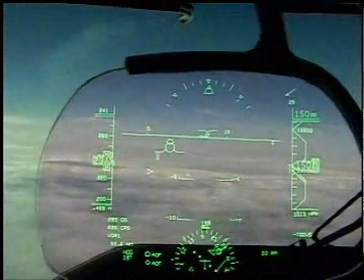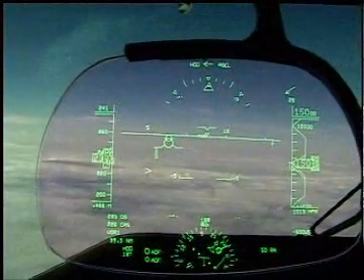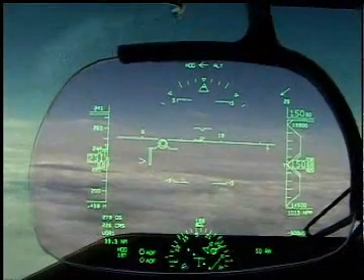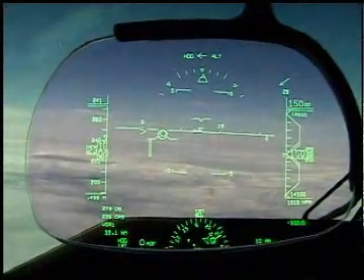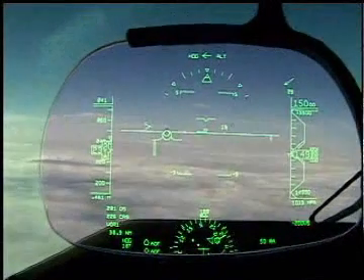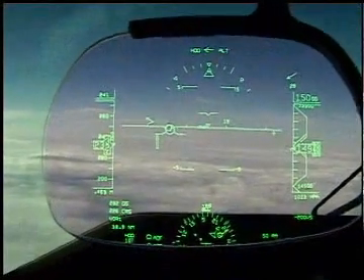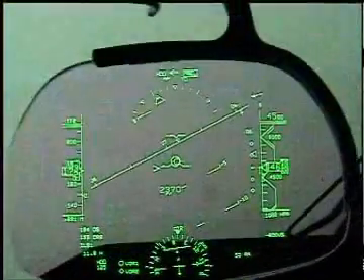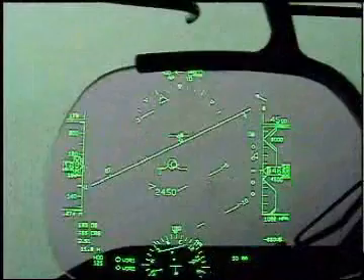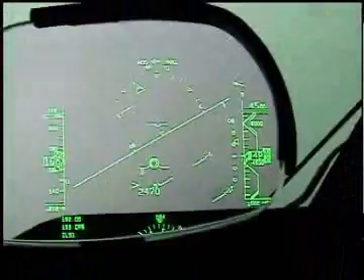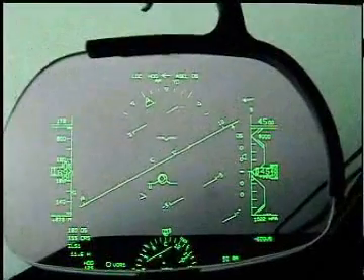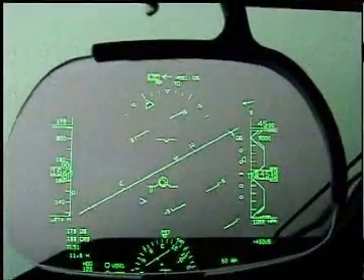Due to the wind at this altitude, the aircraft is flying in a slight left crab angle to track the desired track. This crab angle is evidenced by the lateral displacement of the flight path symbol relative to the aircraft reference symbol. If the crab angle is great enough to cause the flight path symbol to be limited by the airspeed or altitude scales, or the display field of view, then the flight path symbol becomes nonconformal and is displayed ghosted as a dashed line symbol.